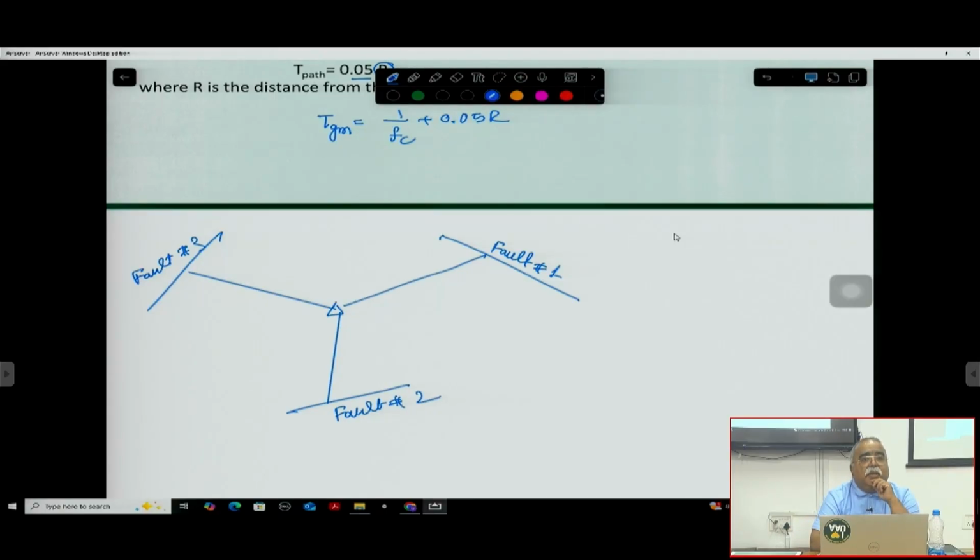So everybody is contributing some earthquake. Now this fault is capable of a magnitude 5.0 earthquake, let's say at 70 kilometers. This fault is capable of a magnitude 8.2 earthquake, at 50 kilometers distance. This might be a magnitude 4.5 earthquake, and this might be, suppose, at 100 kilometers distance, right?